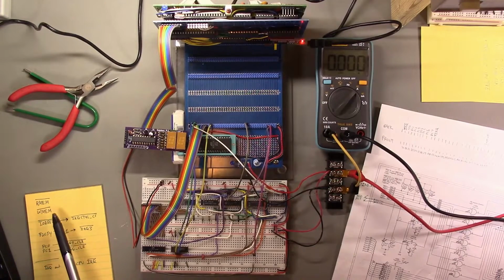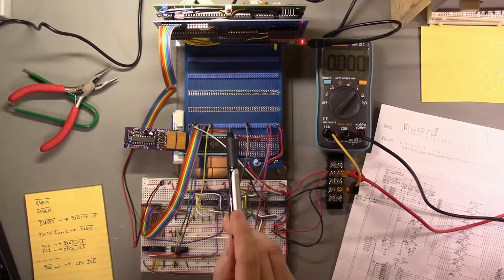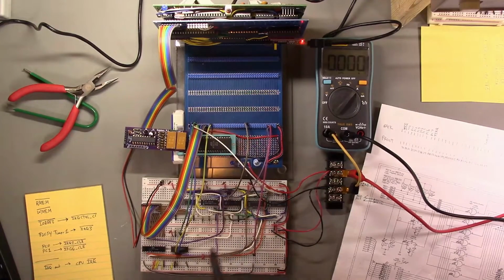Alright, so we've made all of the requisite connections from the main system to the interrupt controller. We've connected the memory read, memory write signals. The IODEV3 signal, which is generated by the address decoding logic, has been fed to become the chip select for the interrupt controller, allowing us to read from the priority encoder and also write to the mask register. The timer 1 output from the 82C54 has been connected to the IRQ3 signal, which is one of the edge-triggered interrupt inputs that the interrupt controller supports.